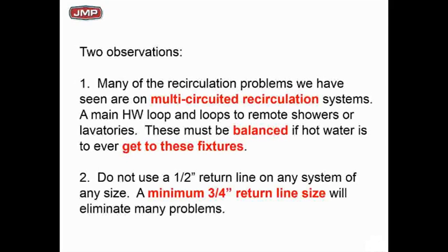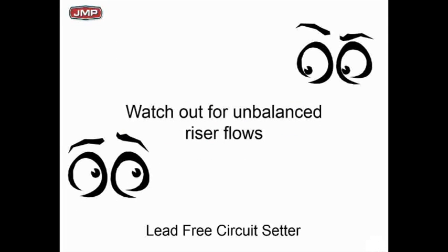In summary, we would really like to see you use a 3/4 inch return. Can you make a half work? Sure you can. But we would prefer to see you use 3/4. It just solves a lot of problems that you're never going to have if you standardize that your minimum return line size is 3/4 inch. So watch out for unbalanced riser flows.